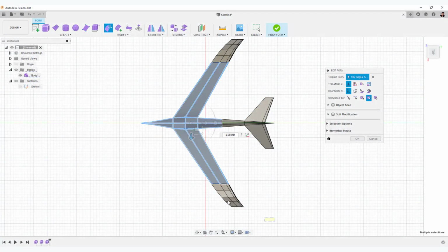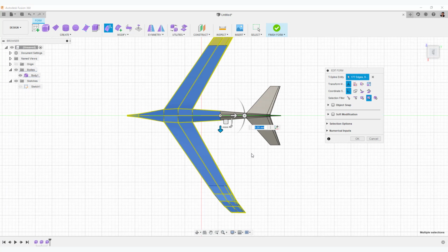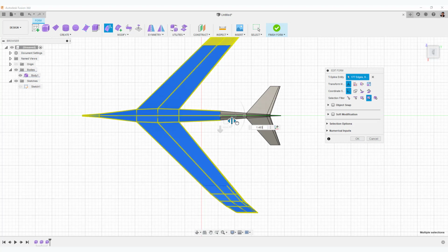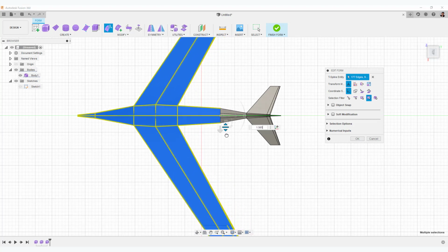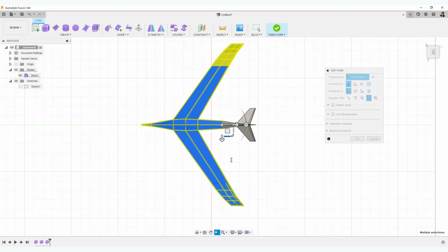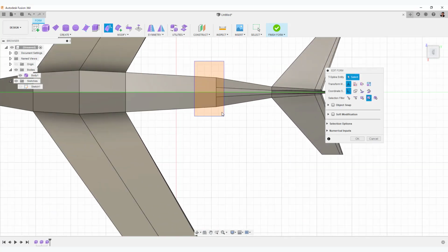Select the part you want to deform first. Move the manipulator's bipod. Select this icon. Move the cursor to the origin you want to deform, snap, and click. Finally, select the check mark. Deforms the body on a horizontal scale. Then the width direction is deformed by the up-down scale. Transitions this part smoothly.